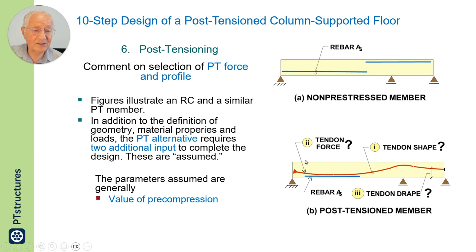In other words, the pre-compression is not determined by calculation. The way we do it in load balancing, it is an input rather than a calculated value. So you need to know how much pre-compression as an assumption. Also, what percentage of dead load you balance.